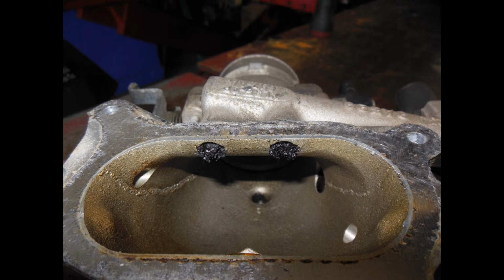Hey, just a footnote about that test I just did. I think probably the proper way to do this is to use a hand vacuum pump so you can make sure that you fully open that EGR valve. As you saw, I just tapped onto the vacuum source at the EGR regulator, and that may not have been enough vacuum to fully open it. Plus, I didn't have those temporary connectors in there tight. I didn't want to take the chance of stretching those boots out that go into the regulator and having a loose connection for the future.